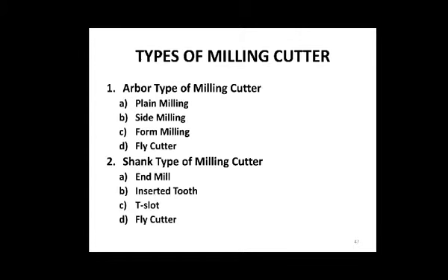Square end cutters can mill square slot pockets and edges. Ball end cutters mill radius slots or fillets. T-slot cutters mill exactly that, T-shaped slots. Shell mills are used for large flat surfaces and for angle cuts. There are variations of these tool types as well.